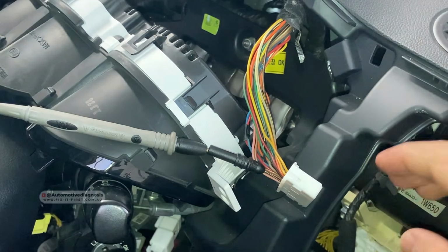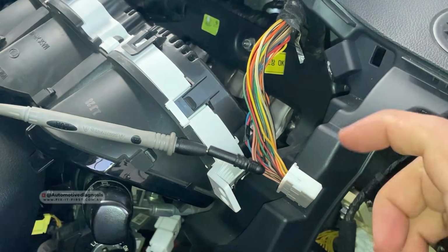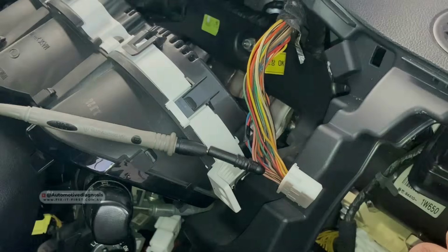If you didn't have continuity or you had any abnormal measurement, it shows you that that piece of wiring is open or there is high resistance in there, which is causing the issue. So you can focus on it and fix it. And that's the reason that control units are giving you the fault code as CAN timeout with instrument cluster.